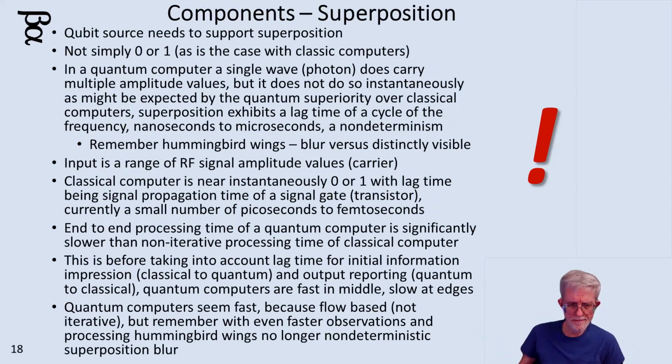Now, superpositioning. In a quantum computer, superpositioning is just a range from what I call 0 to what I call 1. You can actually do that in a classical computer. You can have an array of values that are in a range, and then you can process data on every value in that range. And it's easy enough to do with vector processing to do chunks of that. And if you extended the instruction set using a field programmable gate array, you could actually do your entire range of values as a parallel operation, a single clock operation. But it would require changes to the hardware.